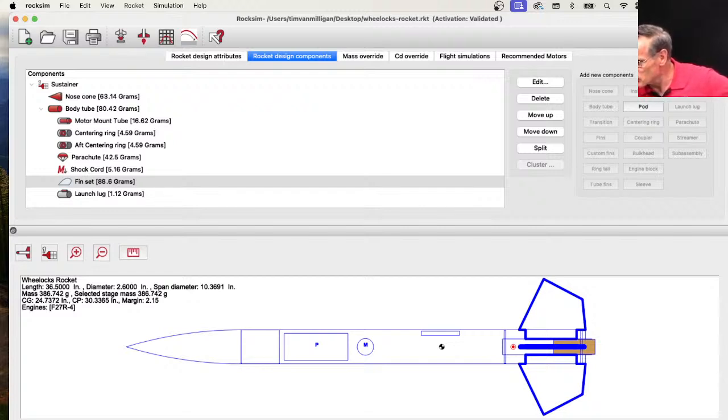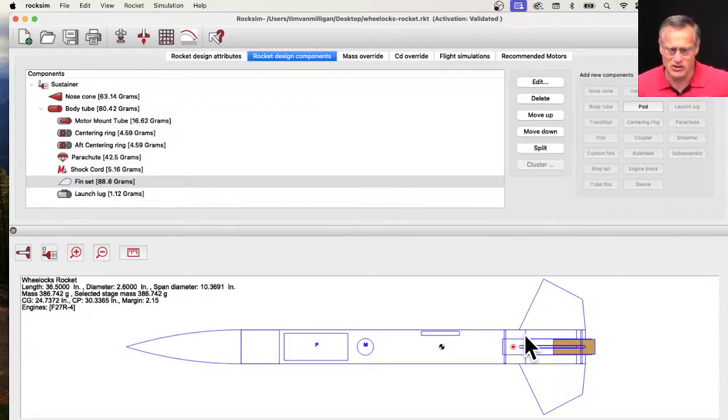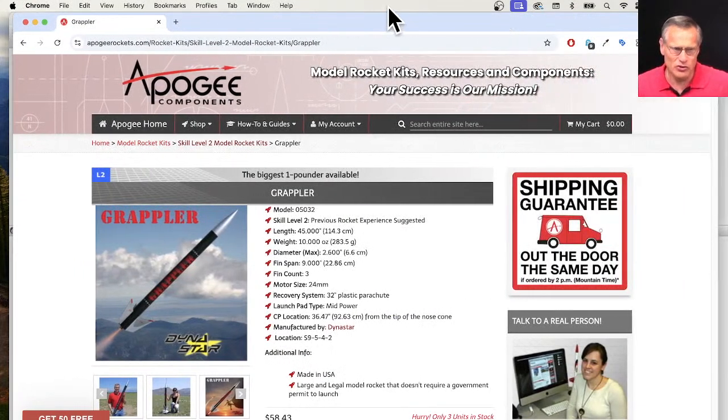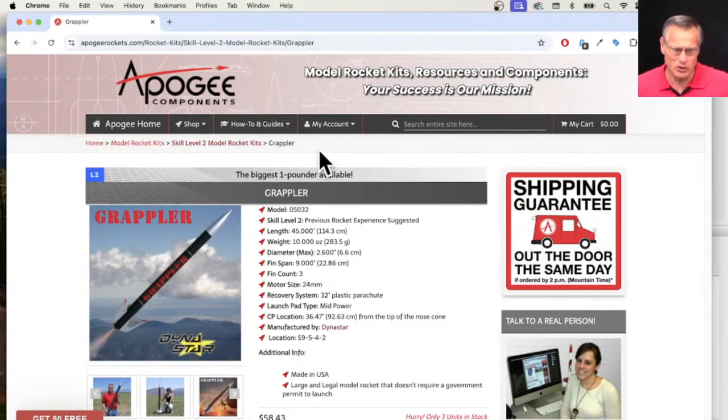Action says, sir, my problem is that I understand CP, but I can't calculate it and its position, for single and multi-stage rockets. Please clear it. Okay, so the center of pressure, if you wanted to calculate it by hand, you need to use what's called the Barrowman equations.